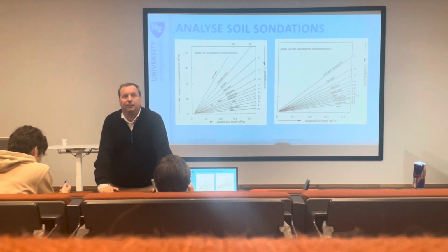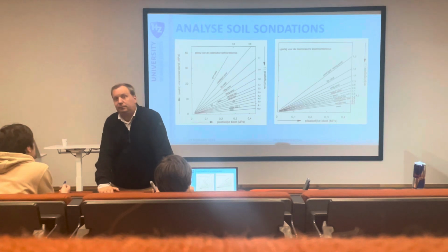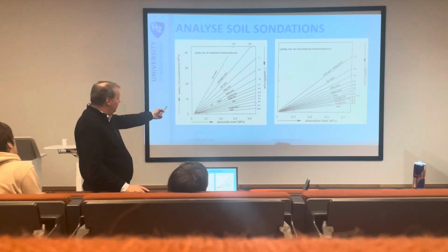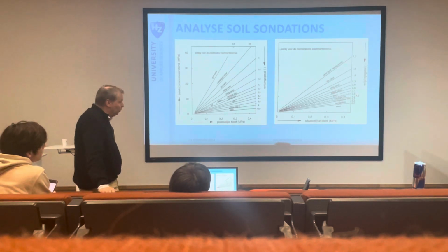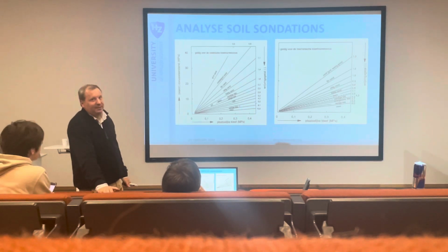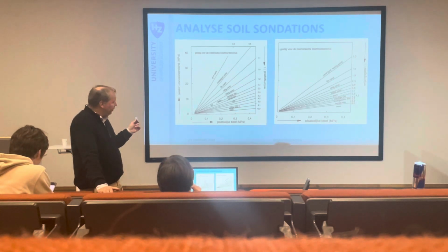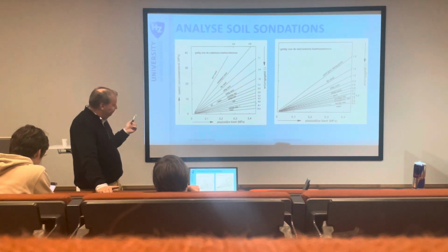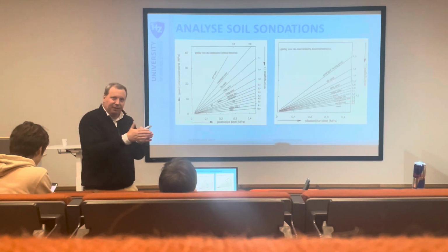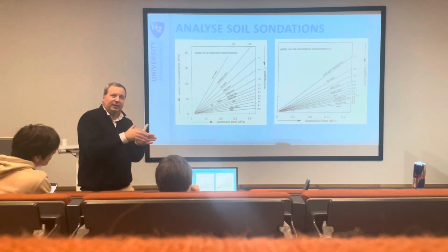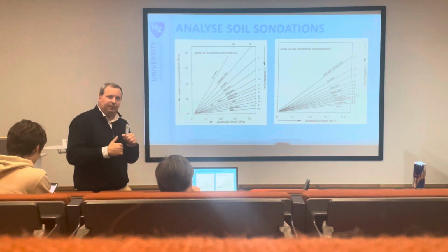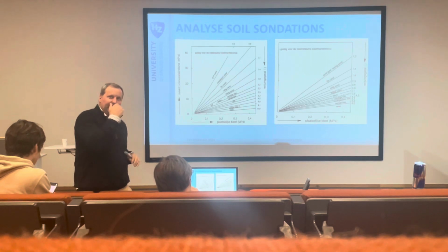Why doesn't the graph start from zero? Well, basically, good question. You actually start with zero. However, when you put the needle in the soil, you already start with a little bit of resistance. That is not counted, so that you can evaluate the soil. That's why we start a little bit after the zero.